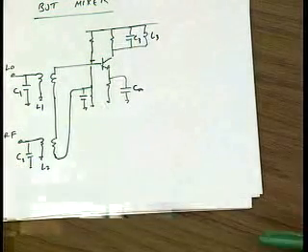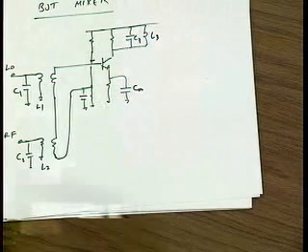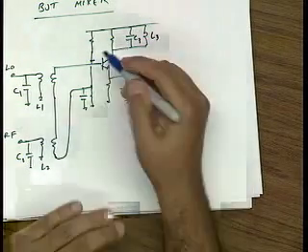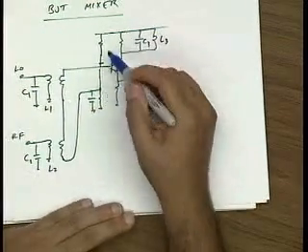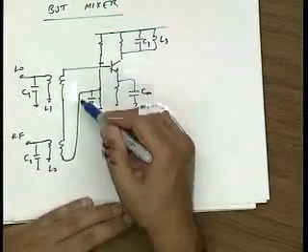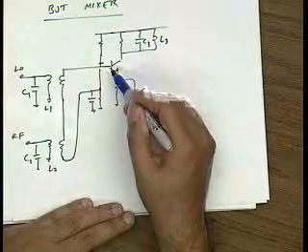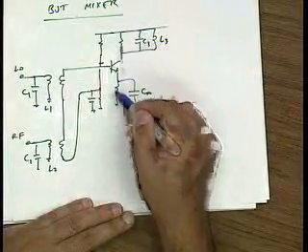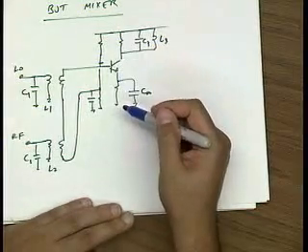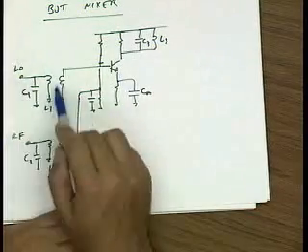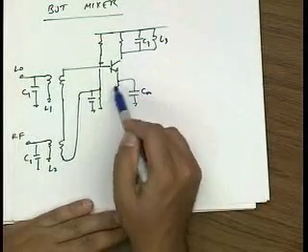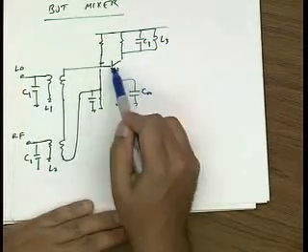Okay? Next lecture we'll analyze this in detail, but right now let's see how the circuit could work. This network just biases up my transistor, and I apply that bias voltage through this transformer, and that establishes the bias point. Of course, I use an emitter resistor here to stabilize the bias point. Then I apply a large LO signal, which will generate a time-varying transconductance in this device.